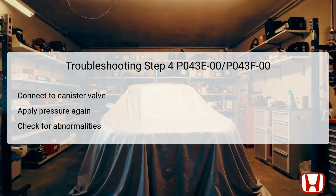The final troubleshooting step involves connecting the vacuum pump to the canister one-way valve after disconnecting from the drain tube. This step is critical as it allows for a second test of the system's pressure management capabilities.